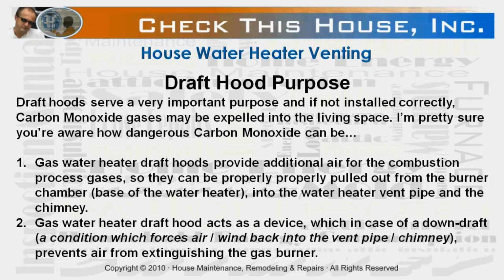The first purpose of the gas water heater draft hood is to provide additional air for the combustion process gases so they can be properly pulled out from the burner chamber, which is at the base of the water heater, and into the water heater vent pipe or chimney. The second purpose of the draft hood is to act as a device which, in case of a downdraft, a condition which forces air, wind back into the vent pipe and the chimney, prevents air from extinguishing the gas burner.